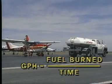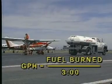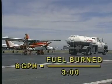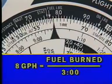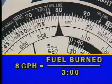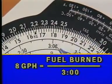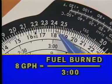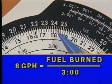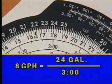Suppose in your flight planning you need to know how much fuel you will need if your destination is 3 hours away and your airplane burns 8 gallons of fuel per hour. Like the speed problem, set the index mark under the rate of 8 gallons per hour. Then find 3 hours on the inner scale, or 180 minutes on the middle scale. Read the fuel required, 24 gallons, directly above this time.